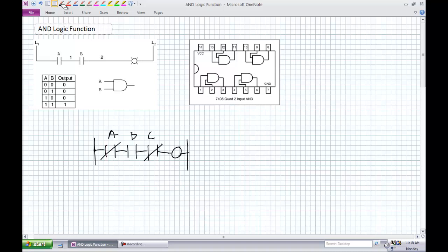Okay, so you need all of them to turn it on. Any one of them can turn it off. Okay, so it's a safety chain, permissive. Very similar to that is that concept of any one of them can turn it off. What if you want an alarm? Let's go back to our sourcing and sinking arrangements.